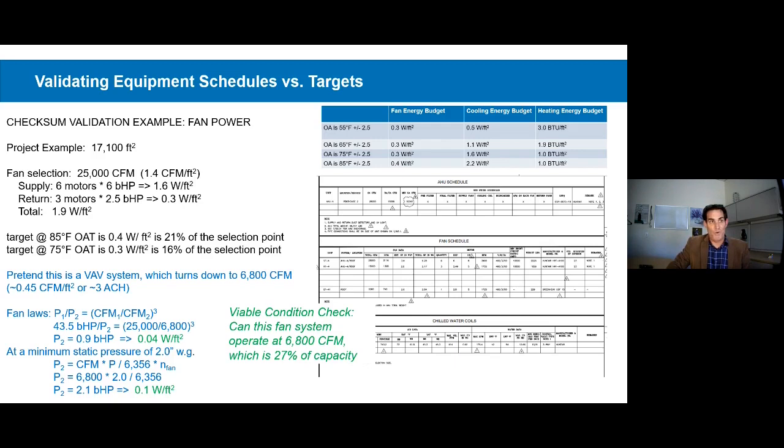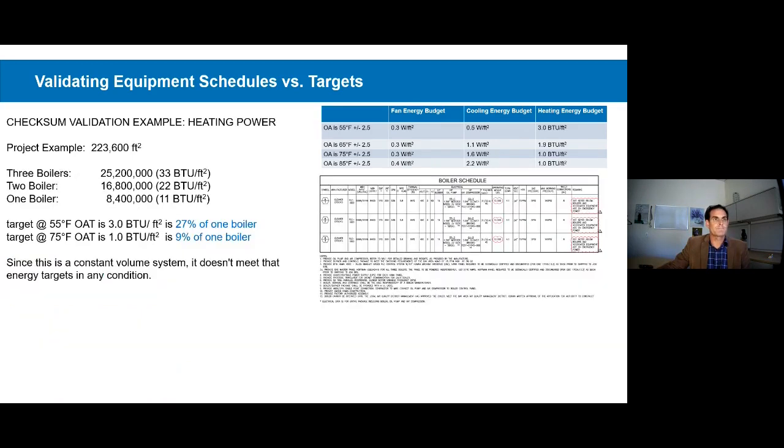It's particularly important in DX units. We have DX units where the manufacturer puts in place a maximum turn down to 50%. So a 25,000 CFM unit is not able to turn down below 12,000 CFM. So those definitely need to be checked at the time that you're scheduling.